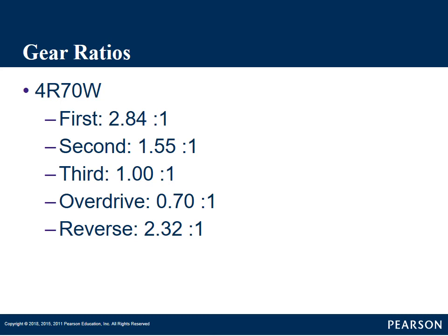As you can see, in most of these, they have a pretty good jump from first gear up to second gear, and then you can see the increments as they're shifting gears. And if you remember from our lesson of when we talked about why we even have multi-speed transmissions, that was so we could match the engine displacement and output to the desired design of the vehicle. In other words, if we have a big 6,000-pound truck, we need some low gears, we need to get the vehicle moving, we want our power at the lower speed, more torque at lower speed, lower RPM, to get the vehicle moving, because those vehicles are going to be used for pulling stuff.